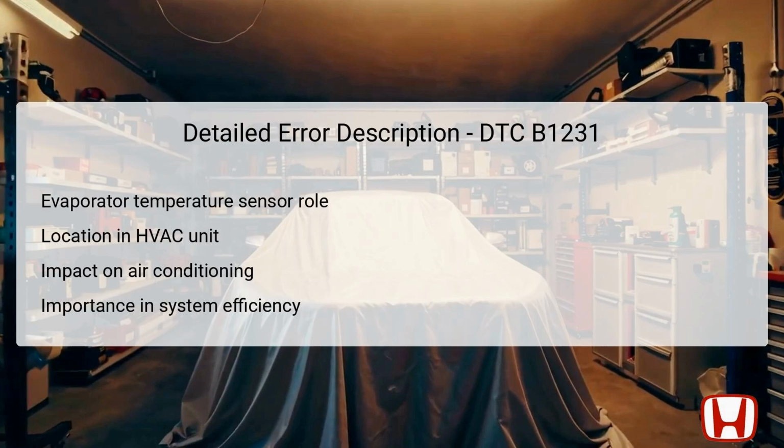The evaporator temperature sensor is a vital component in the HVAC (heating, ventilation, and air conditioning) system of the Honda Accord. It is strategically positioned within the evaporator assembly to accurately measure the temperature of the refrigerant. By gauging this temperature, the sensor provides critical input to the climate control unit, which adjusts the AC system settings accordingly to achieve the desired cabin temperature.